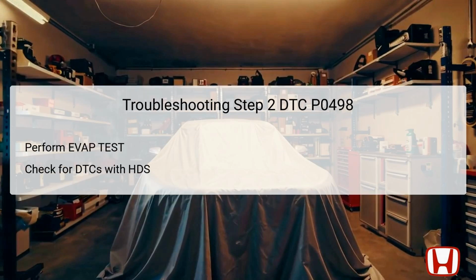In the second step of troubleshooting for DTC P0498, select the EVAP test from the inspection menu on the HDS. This diagnostic procedure targets the specific operation of the EVAP system, allowing for a close examination of the vent-shut valve's functionality. During the test, perform the EVAP CVS on command, which specifically activates the single solenoid responsible for the vent-shut valve's operation. After executing this command, once again, use the HDS to check for any pending or confirmed DTCs.